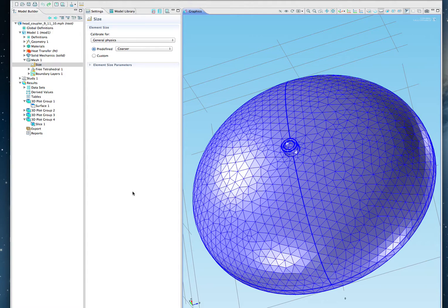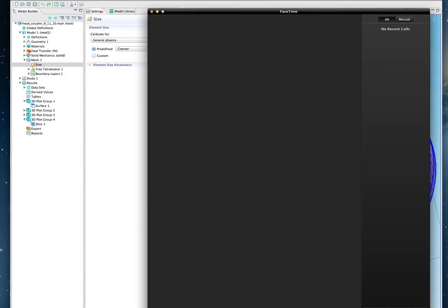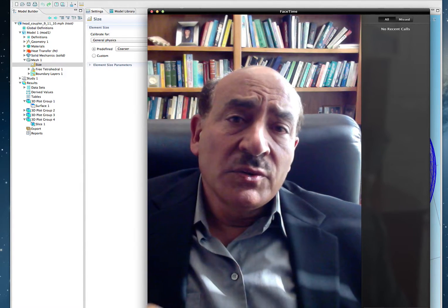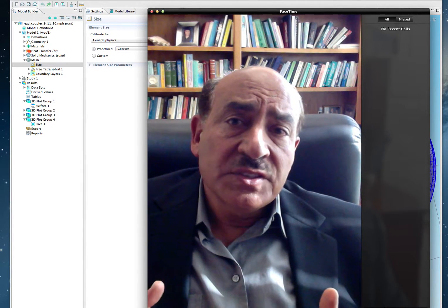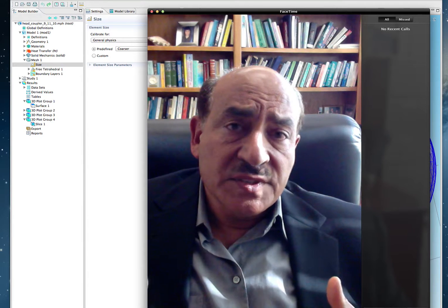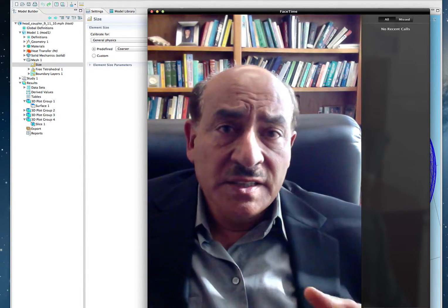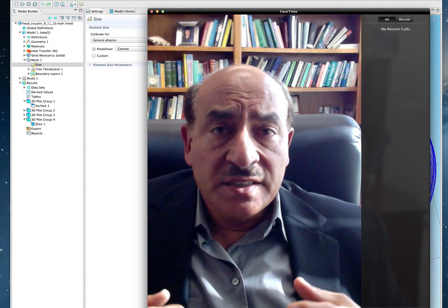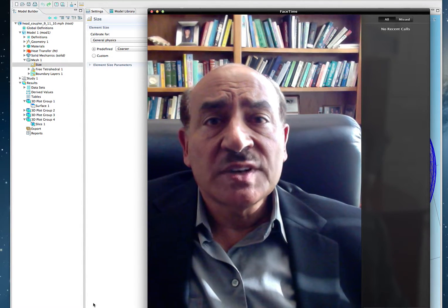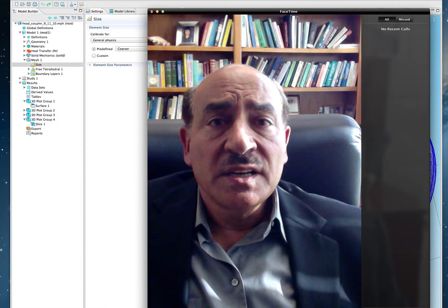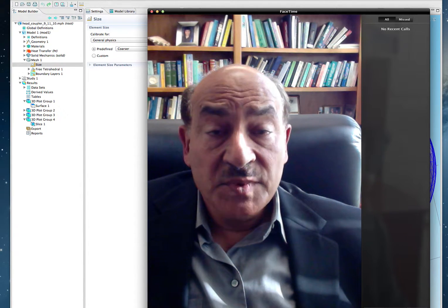So initially you can solve the model with the coarse mesh, and then after you solve it and get some results, you can make the mesh finer and run it again and get more accurate conclusions from your simulations.